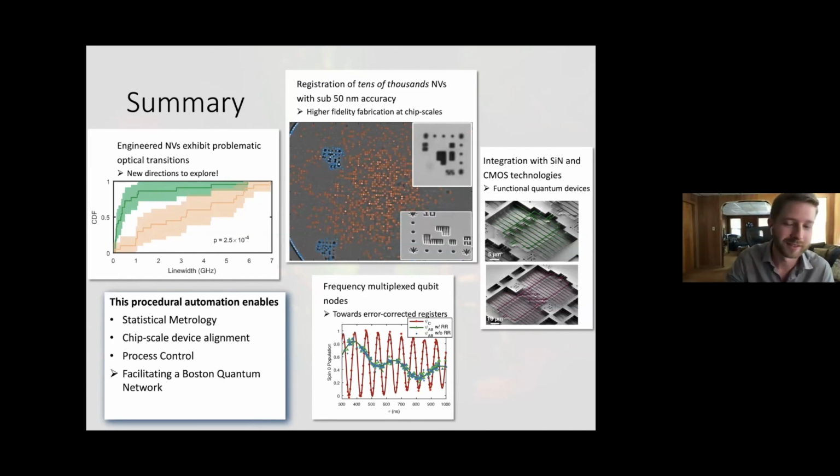Now, to fix that, it is possible. The use of cavities would help drastically. In these early demonstrations, these actually aren't cavities yet. These are just nanowires. So if you remember, the cavity is basically a nanowire with holes. This just doesn't have the hole yet. And so we don't get any benefits from putting it in a cavity yet at the device layer.